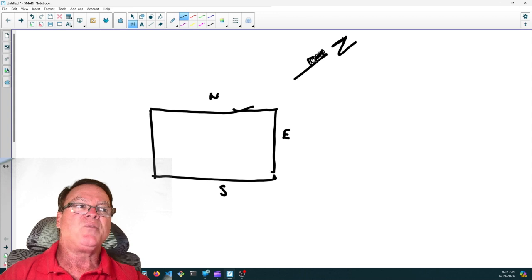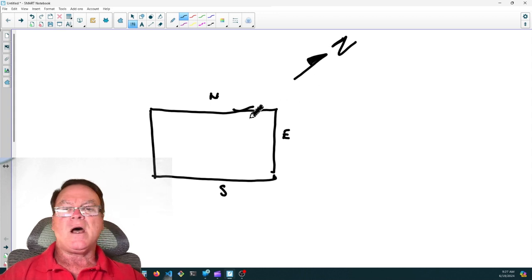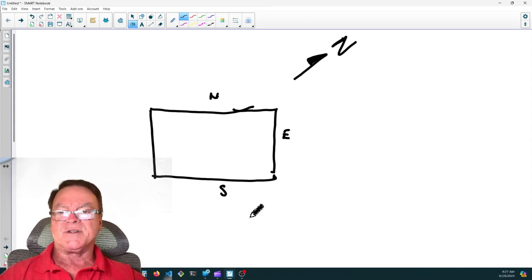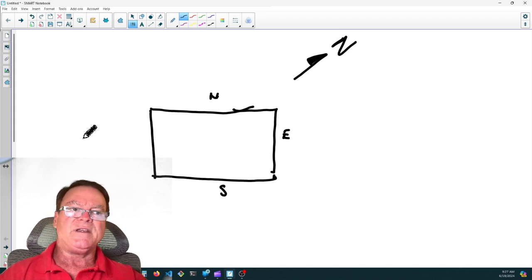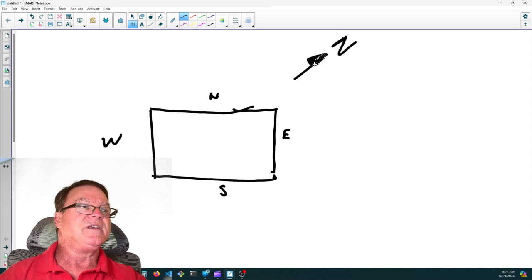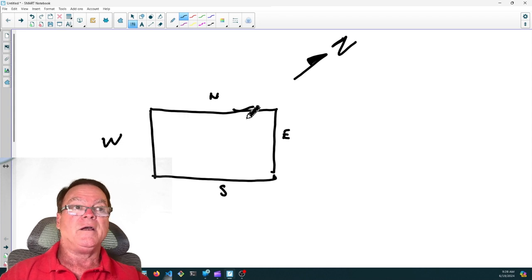They don't always put that on drawings. If that's not on the drawing, then the top of the print is north and the bottom of the print is south. The right is the east and the left is the west. But you can see they don't have to position their buildings true north. They can put it catty corner on the lot.